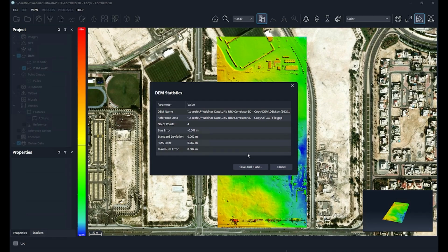Again, these GCPs weren't the best GCPs. They were on the corners, but they weren't really meant for this particular project. So sometimes, you have to make the best of what you have. Otherwise, I would have probably preferred to go with finding some lidar data, some external DEMs, and other reference orthos, and then try to do that. But again, for the extent of the project and the AOI, these GCPs were enough. The absolute accuracy that we needed for this project was met.